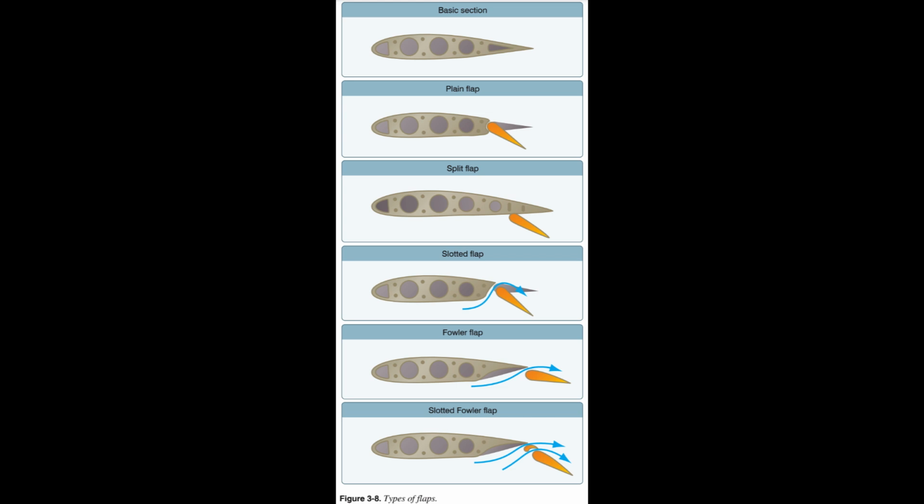Flaps extend outward from the fuselage to near the midpoint of each wing. The flaps are normally flush with the wing's surface during cruising flight. When extended, the flaps move simultaneously downward to increase the lifting force of the wing for takeoffs and landings.